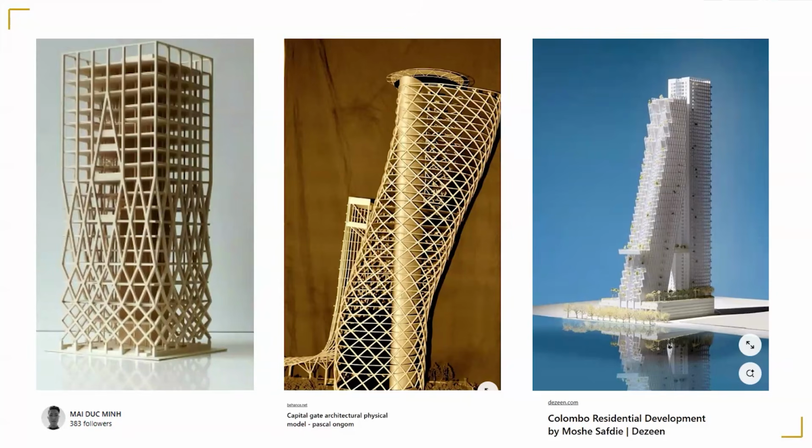And this is another example where the building is actually going like this and the core is holding it down. So you cannot design a building like this as cantilevers, because there are no columns here. So this whole diagrid is a cantilever anchored to the frame, to the core.